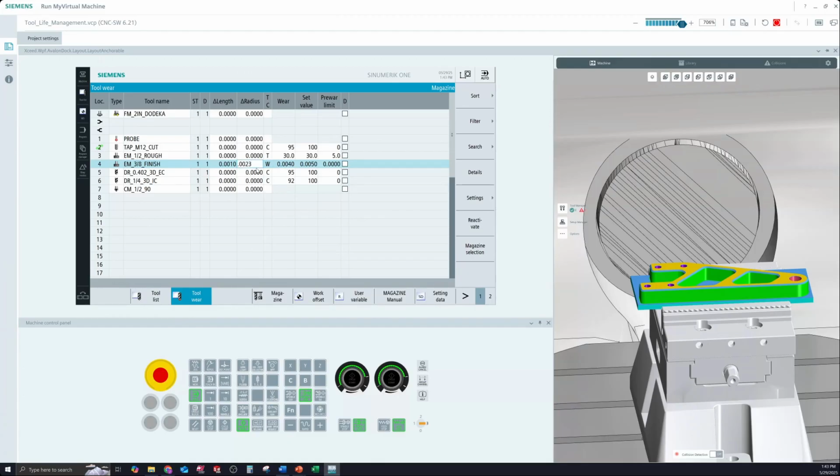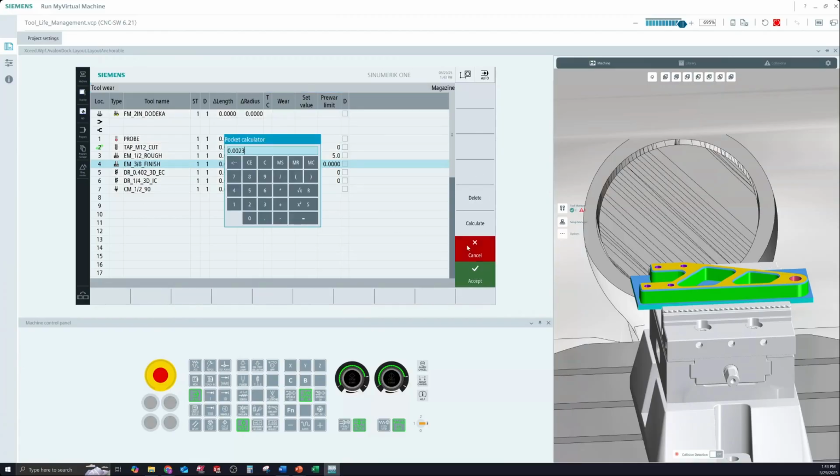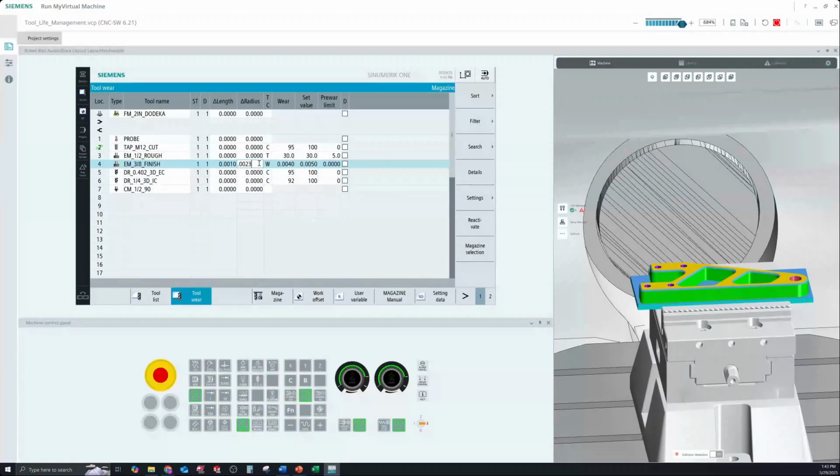So if I go to 2 thousandths, oops, sorry, hit the wrong button here. If I go to 2 thousandths, you'll see it go to 3. Go to 3, so forth. Pretty easy. All the way to 0. Now, once we reach 5 thousandths of cutter comp, we say, well, you've reached your limit. You have no more. Now I'm going to disable this tool, just like the others.